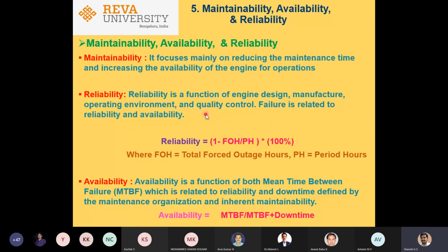That is very important. For example, if we are able to take the life of this said engine to around 3,400, if we can pull it to 3,550 or so, touching the design life, that means the maintenance has done an exceedingly good job. So reliability and availability are very critical metrics from a maintenance and operations perspective.